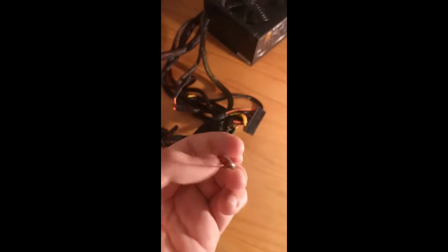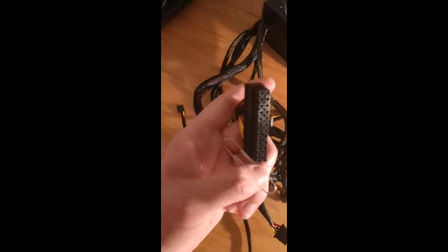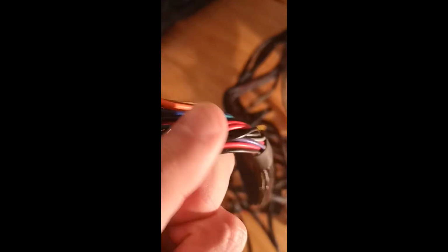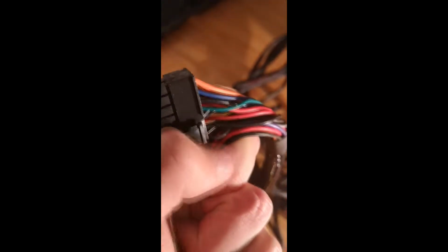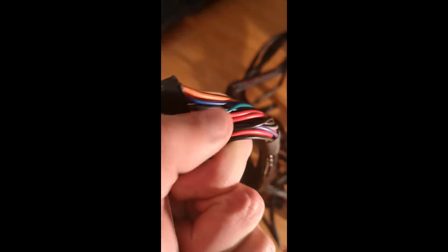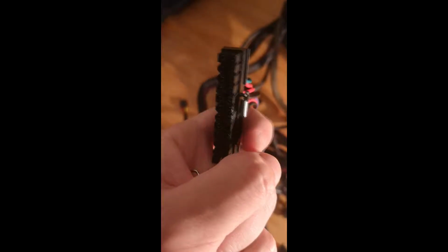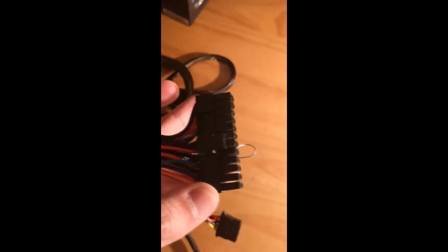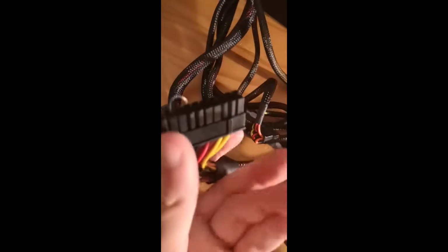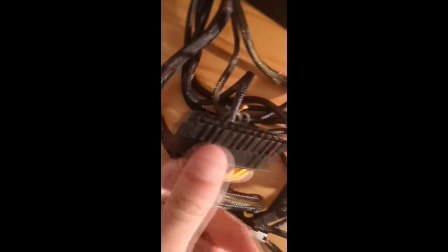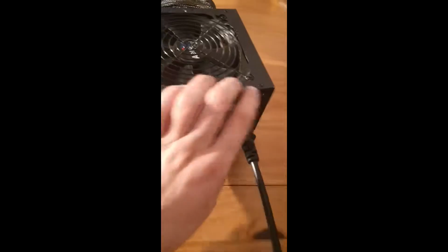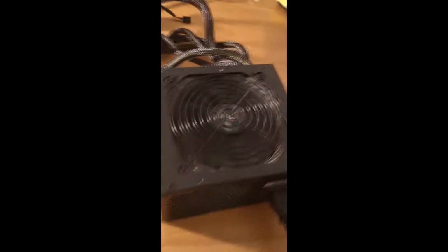Now that you've got all the main components installed on the board, we might as well test for errors. Take the 24-pin connector off the power supply and insert a paperclip into the connector, shorting the green wire to a black wire next to it. This tells the power supply fan to turn on if it's outputting the correct voltage. Make sure the paperclip stays in place, plug the power supply into the wall and hit the on switch. Watch the power supply fan, and if the fan starts to spin, this means that it works.